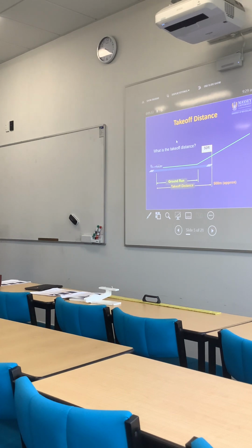Now our diagram here perhaps doesn't give it justice, but this little distance in here between the point of getting airborne and climbing to 50 feet can be significant on some days. Sometimes it is almost the same distance as what was actually required to get airborne. And we'll hopefully see that in the calculation we perform later on. So it's not just the physical distance that we're on the ground that we need to account for, it's the distance to climb to 50 feet as well. And that will change depending on conditions and depending on the aircraft.